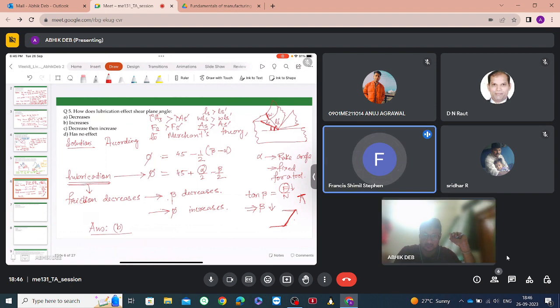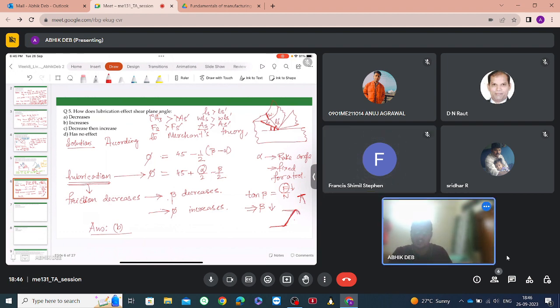Okay, sir. So actually, it will be at the radius point, in the nose position? Yeah, in the nose position, but the nose is not essentially doing the entire cutting operation. The cutting edge along with the nose is where the tool will come in contact with the workpiece. The nose radius is given, along with the angles at the end cutting edge, so that there is a gradual contact of the tool with the workpiece, but the cutting action takes place from the nose along with the cutting edge. That is why it is called the cutting edge.